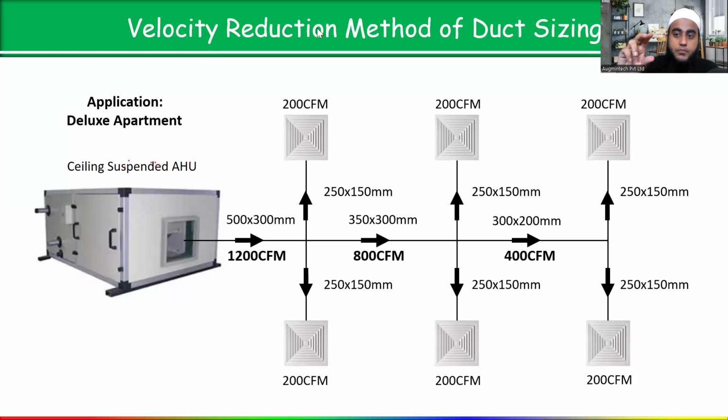So minimum as per standard is 100 mm minimum height. Okay. Sayyid Saad Ali, is it clear now? This thing, how much minimum height we have to consider for duct? Don't go less than 100 mm, means near about 4 inch.